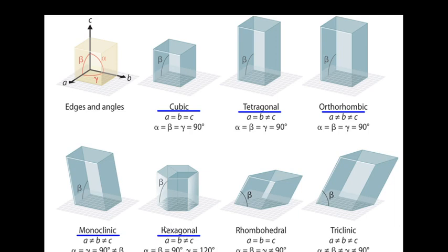The same crystallographic structure, a fundamental crystal that is hexagonal, but you can also look at it through a different window: it is a combination of three tetragonals facing each other. So this is one dark zone, this is a rear one, this is another tetragonal, and this is a third tetragonal, where everywhere you find A and B are equal. Here A and B are equal, right? This is A, let us say, and this is B, but this would be its C. If I talk about this dark one, this is A, this is B, and the vertical will be the C. So A is equal to B but not equal to C.